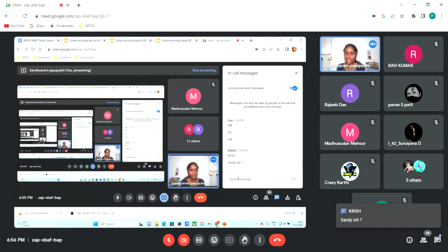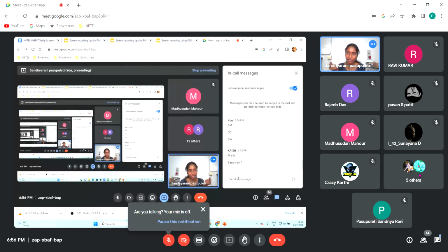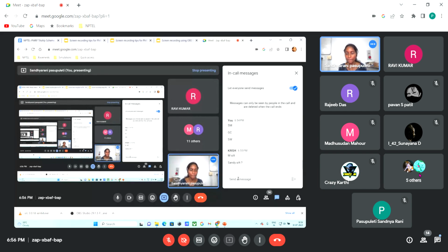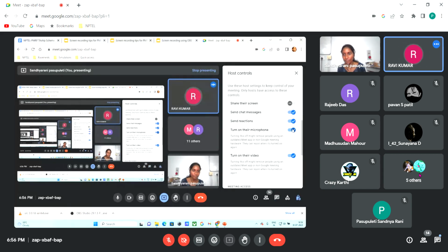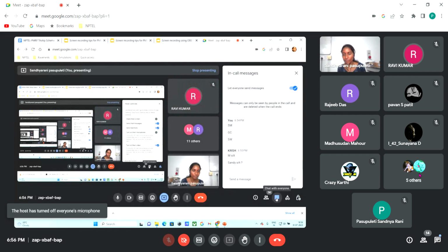So, the symbol looks like SM, but you have to read it starting from the latter symbol. S is the sand, M is the silt, but we have to call it silty sand. What that represents is, the type of soil which we have is a sand, but in this sand, the major portion of the soil is silt. So when I say silty sand, that means in the